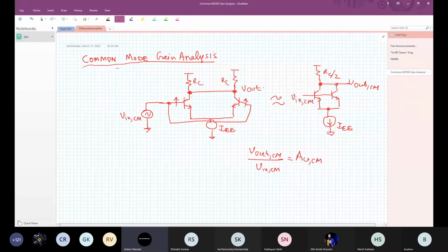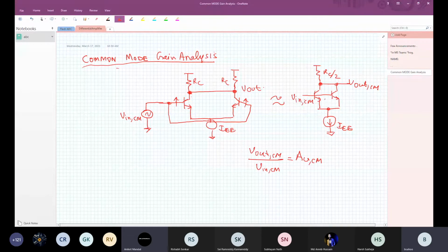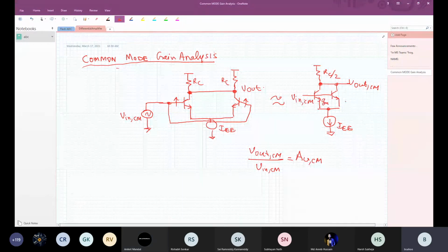It's a GMRC. GMRC by 2. It wanted to be GMRC because it's 2 GM. So those two are in parallel. Those two are in parallel. That is a good point. So this is GM and GM, so it becomes 2 GM.